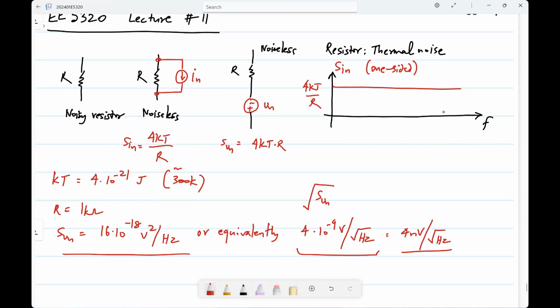Okay, so finally, when you have to calculate variances, the noise has to be band limited in some way. Otherwise, you just leave it at spectral density, right? This white noise is just a model. Integrating that from 0 to infinity makes no sense. You will always get infinity. But in real circuits, you will always have band limiting, as we'll see. Okay. Any questions about this?